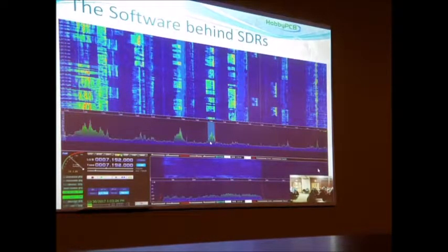And another nice thing about HD-SDR is that you can collapse any of these windows. You can collapse it all the way down to just a little control panel, which means it also turns off the processing behind that window. So you can use it for low bandwidth remote control capabilities. With this piece of software running on your PC and an Ethernet connection, you can operate your radio from anywhere with just a remote desktop type function.